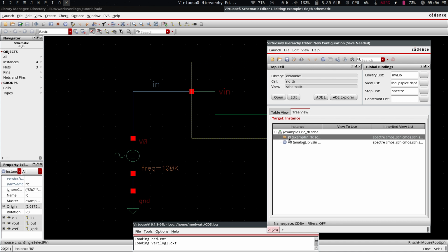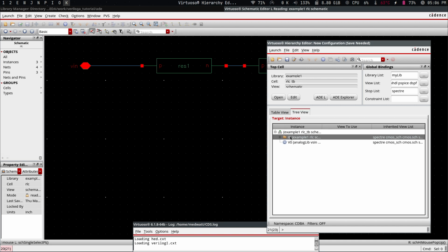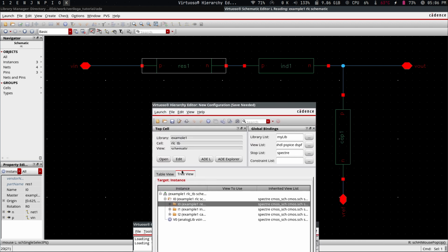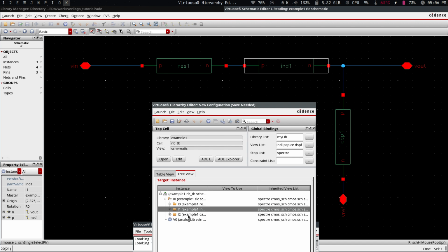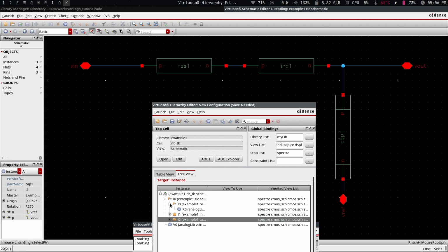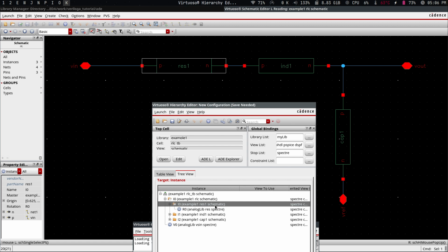And then if we go inside this I0, we can see that internally we have this. You can see that as I'm pressing on it, it's doing that. Then we have I0, I1, and I2. Very good. And then inside this I0, furthermore, we also have another component. So this R0 that you see here is basically the schematic view of the resistor, because at the moment we have schematic chosen. So it's referencing the Cadence implementation of the resistor.